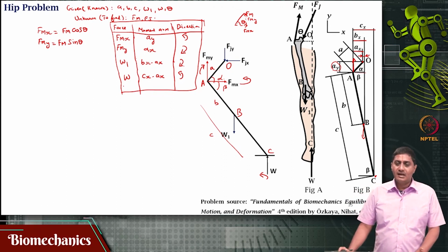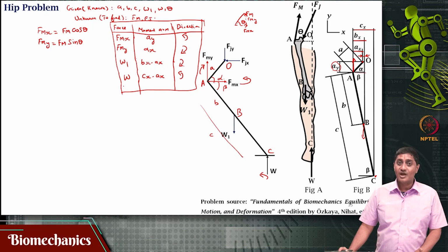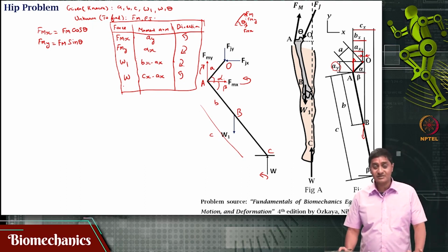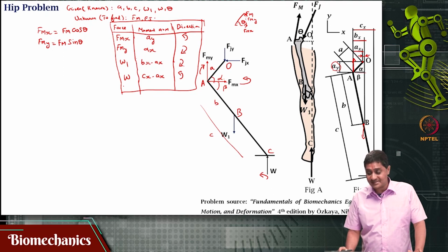Note, I do not know what Ax, Bx, Ay, By are. I only know A and B. The corresponding alphas and betas are given. Now, not only the forces have components, the moment arms also have components. So, I need to write out Ax, Ay, Bx, By in terms of alpha and beta respectively. Because the moment arms have components, I need to do that.